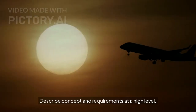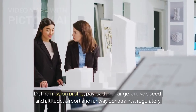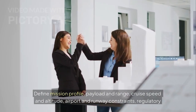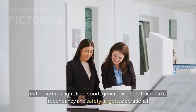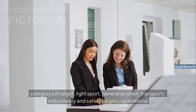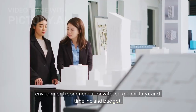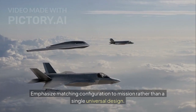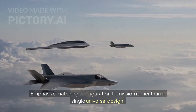Describe concept and requirements at a high level. Define mission profile, payload and range, cruise speed and altitude, airport and runway constraints, regulatory category (ultralight, light sport, general aviation, transport), redundancy and safety targets, operational environment (commercial, private, cargo, military), and timeline and budget. Emphasize matching configuration to mission rather than a single universal design.